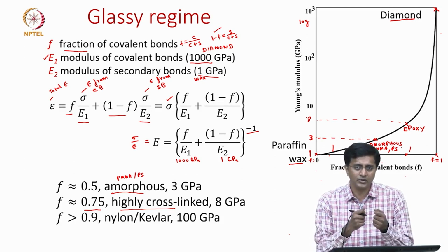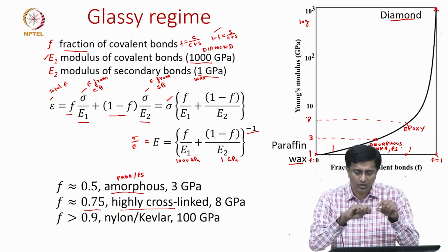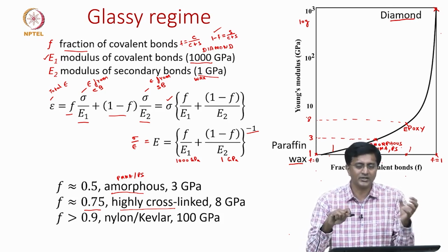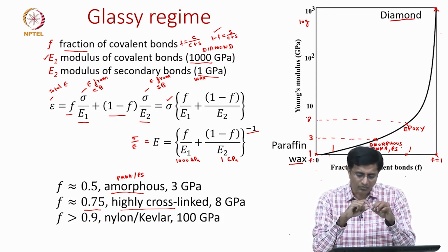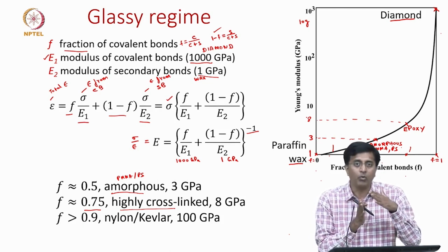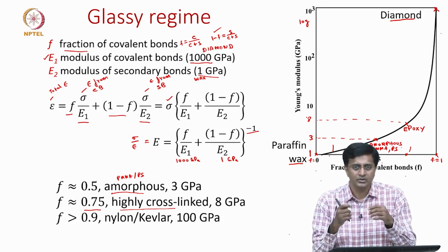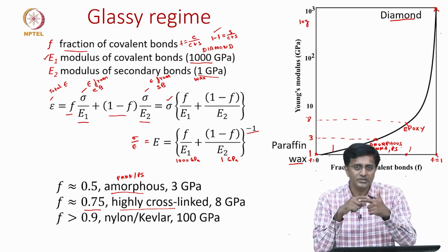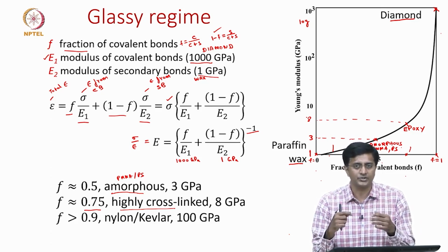Fibers are formed either through extrusion, which means through a small orifice you pull out the fibers from the other end, the molten polymer. But what is happening while you pull out? While you pull out, all these molecular chains are aligned in the direction of the pull. So, what do we have in the molecular chain? The backbone carbon primary bonds, or the covalent bonds.